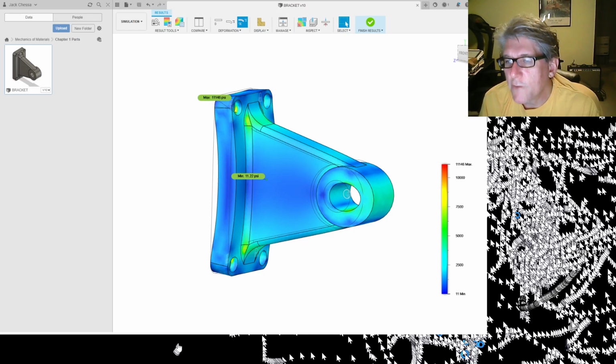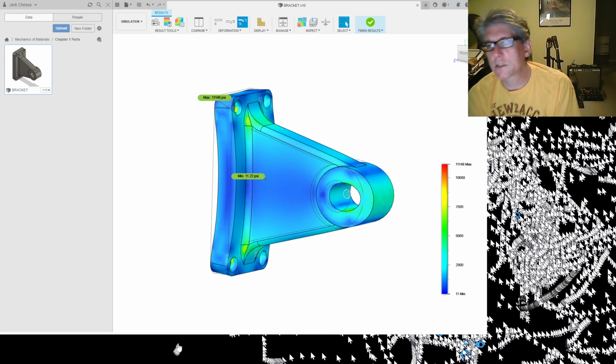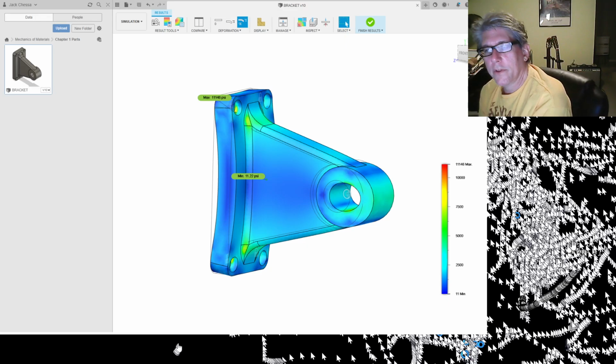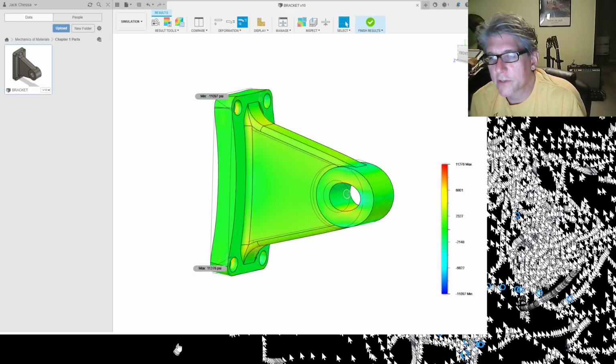And there's different types of stresses. So we're not quite there to discuss these. For now, well, the von Mises is like an effective stress. You'll cover that in design. But the way this bracket is, here is the X direction. So you could look at the normal stresses in the X direction. These will be close to the stresses you'd calculate by P over A.